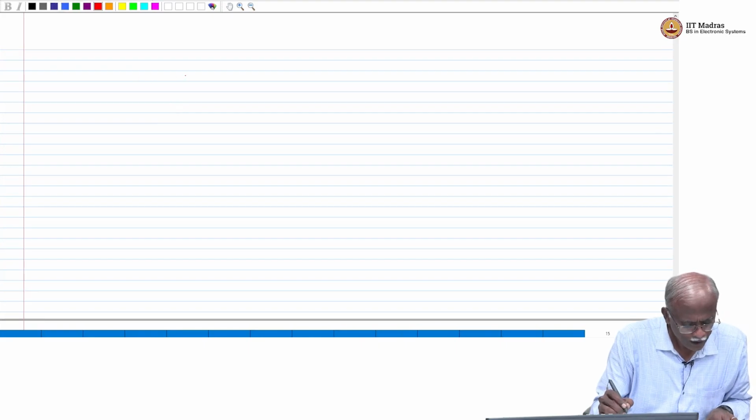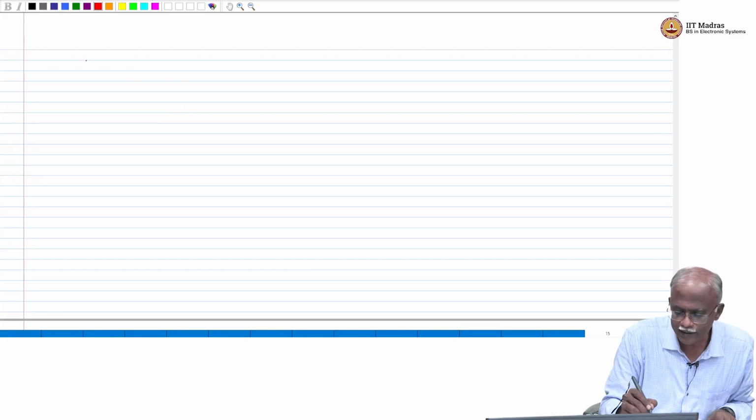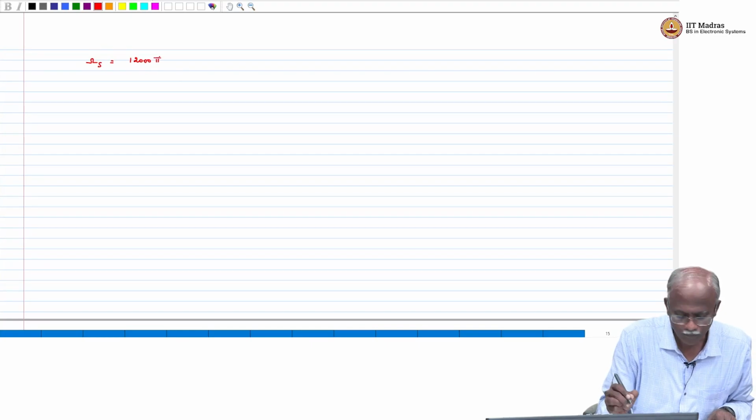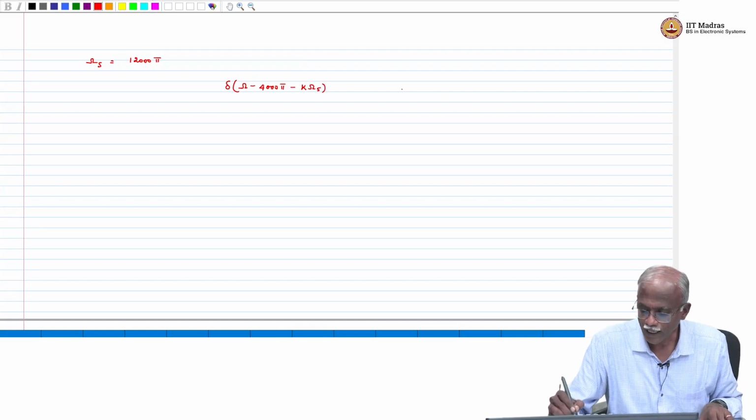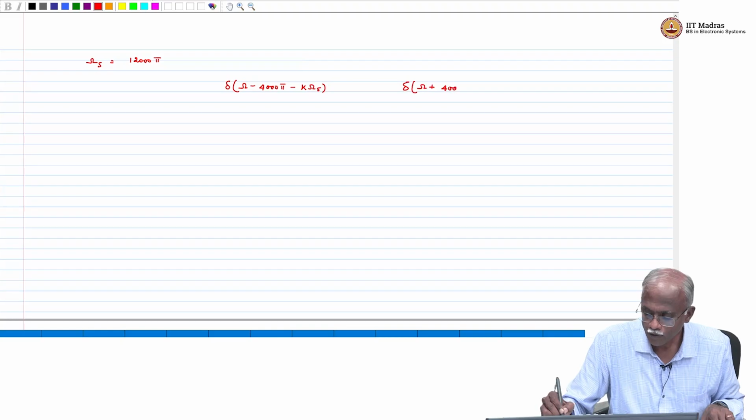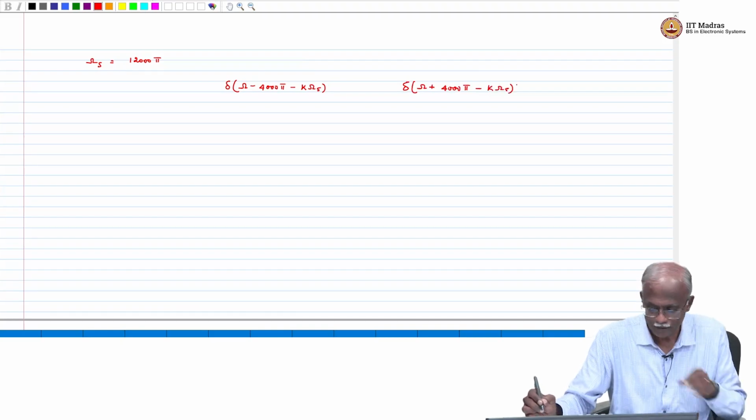So what we are looking at is a sampling frequency which is 12,000 pi. We have the deltas sitting at omega minus 4000 pi minus k omega s, and another delta sitting at omega plus 4000 pi minus k omega s.